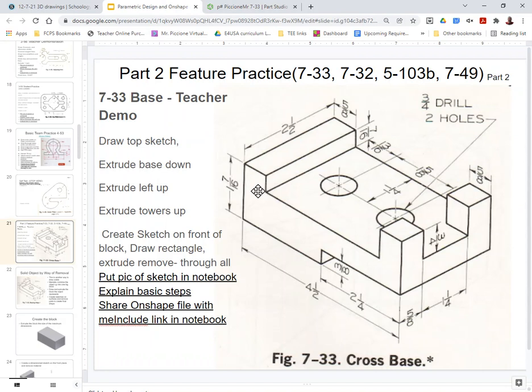So now if I look at my shape in 3-dimensional mode, I see that the shelf is 1 7/16 tall. The squares on the sides take up 3/4. And the shelf sticks up 7/16 beyond the base measurement here. Well, if I know that this is 7/16 here, and this is 1 7/16, the height from the bottom to the base is 1, but instead of just typing in 1, I'm going to put in the math so that I'm familiar with how to do that technique in case it's not as easy as 7/16 minus 1 7/16.